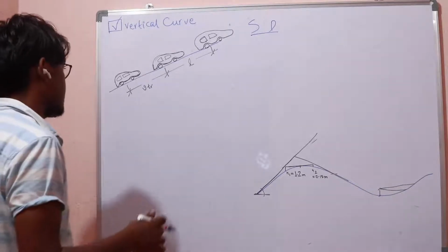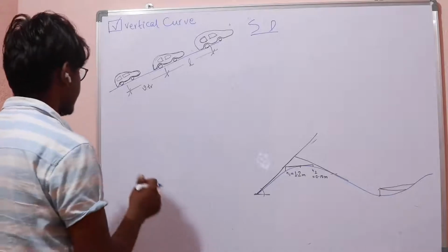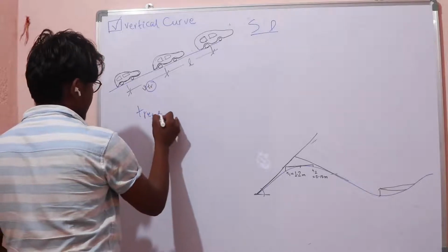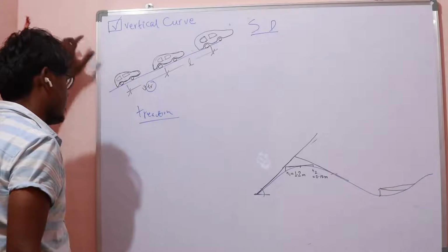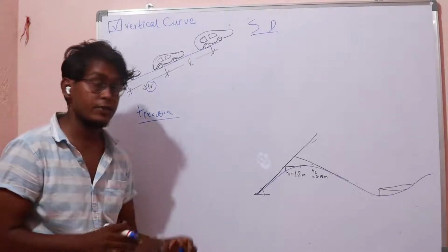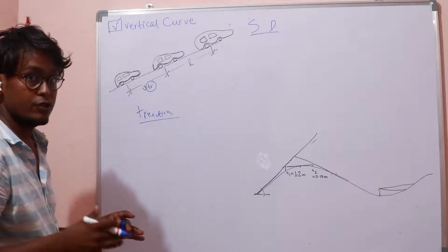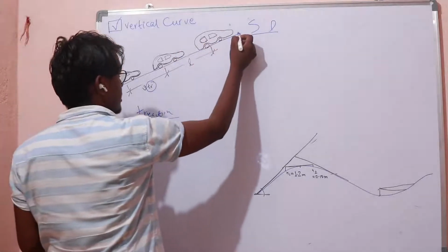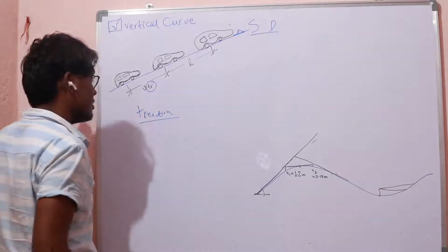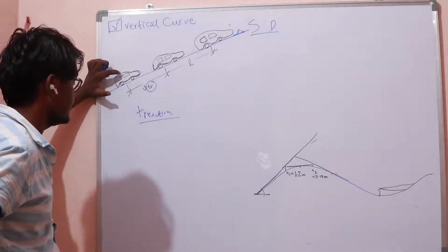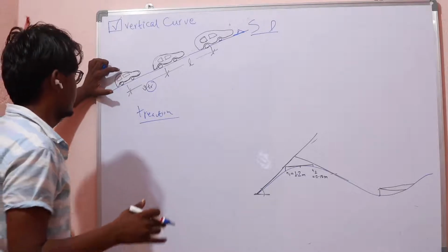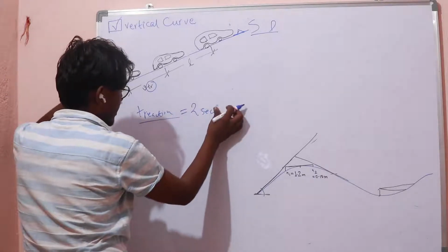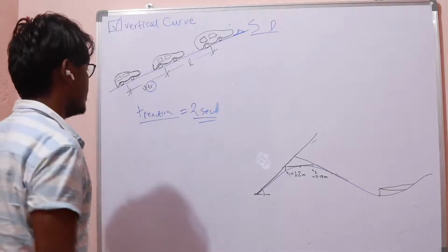So what is being done here is that first this is T_R, reaction time. This is the time which the driver requires to decide whether to apply the brake or not. So this is the reaction time. Suppose the object is here. He has to stop here, and the driver is here. Then he decides to apply the brake. This is generally about 2 seconds. He takes generally 2 seconds to see the object and then decide to apply the brake.